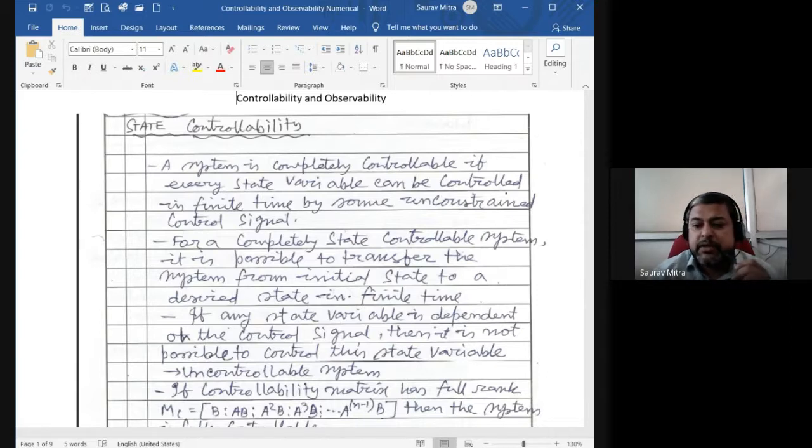It is the solution of the system where no external forcing function is given, only the initial conditions. So if I say iL and vC, there might be some initial current or capacitor voltage already stored in the system before you applied any input. They are responsible for producing the transient response, or zero input response, of the system.